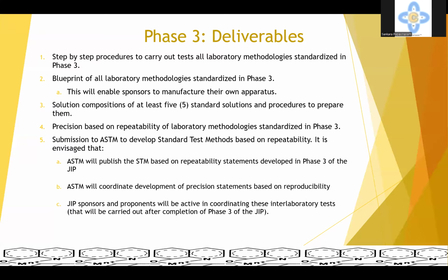So much so that some of the other industries, for example, offshore industries like Navy and Marine, have standardized solutions for their corrosion testing. For example, ASTM has a standard for artificial seawater preparation. So don't take seawater from the ocean, but prepare it artificially in the lab if you are going to do corrosion testing.